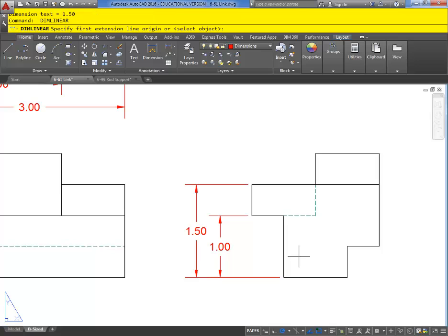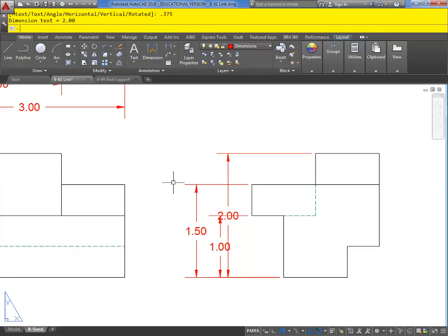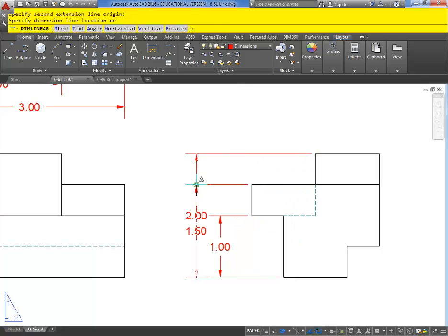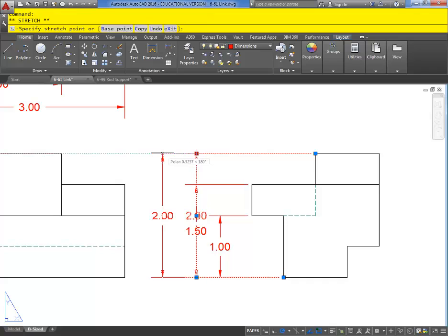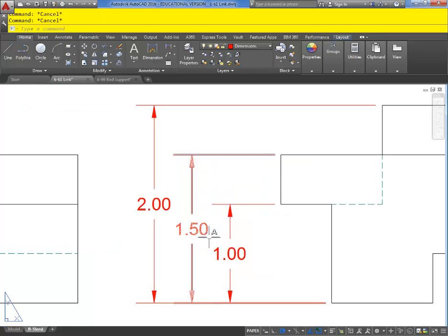So this one's not too bad. Of course, when I want something to look bad, it won't. And again, I'm going to track off of this one since it's the outermost spot. Oh, I only went 3/8 from there. So sometimes another thing that I'll do is I'll actually place it and then move it. So I'll make this dimension and I'll actually snap to this one. And then I'll grab its grip and then bring it out another 0.375. Now this actually looks pretty good, but sometimes you might find that you might need to grab the text itself and move it up or down or left or right to further pull things apart and have them look better.